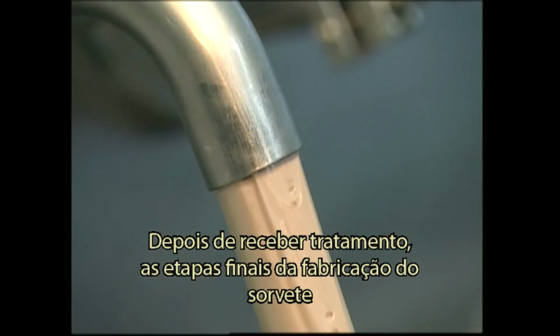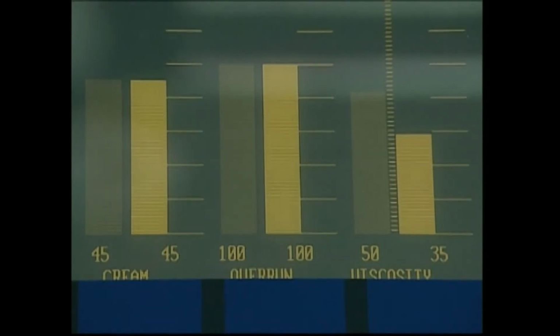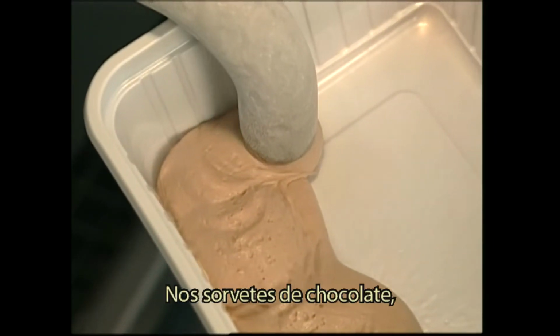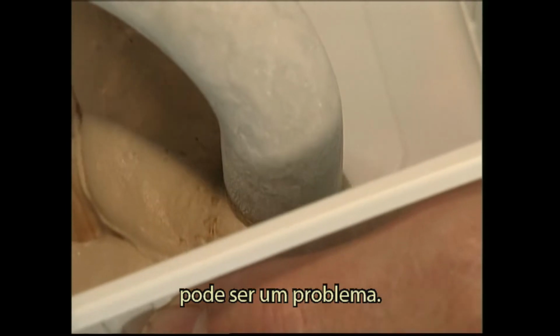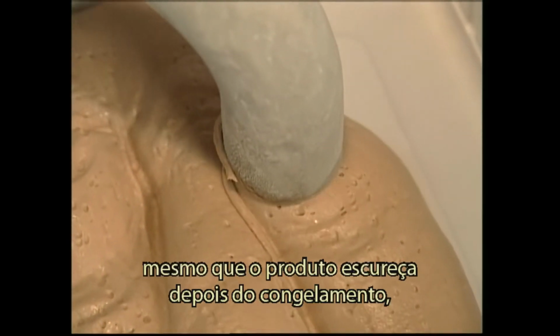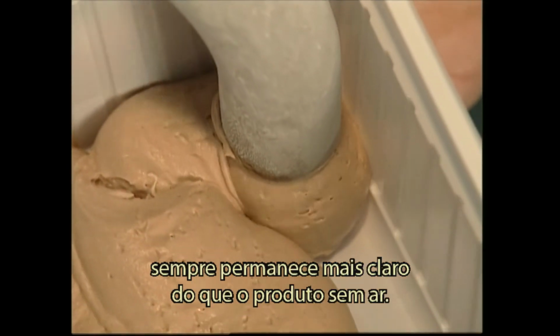After aging, the final steps in ice cream manufacturing are related to the freezing of the product. All ice creams contain some additional air or overrun, which is introduced when the product is in the freezing phase. For chocolate ice cream, the fading of the ice cream color resulting from the introduction of the air is sometimes a problem. It's inevitable, and after freezing, the product darkens, but always remains lighter than the product without air.